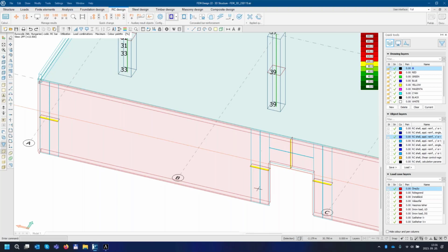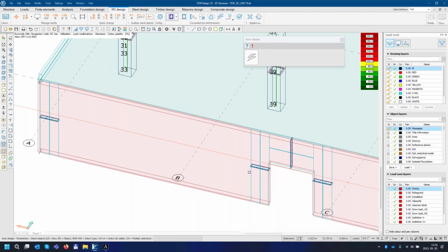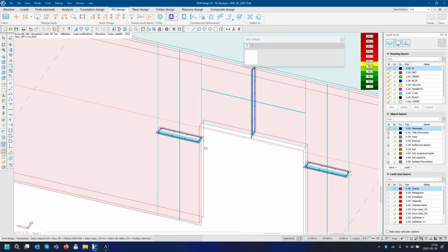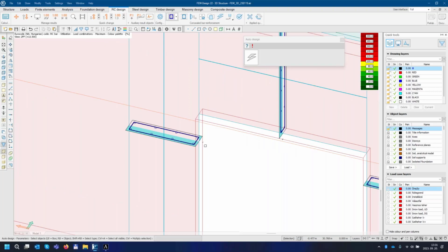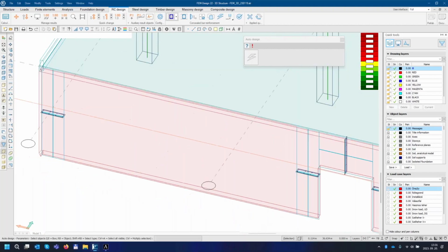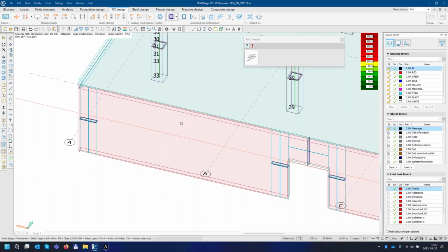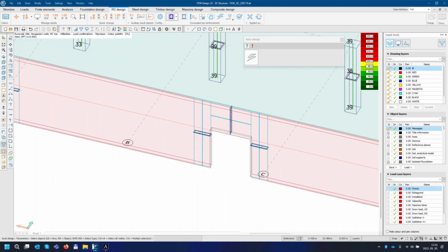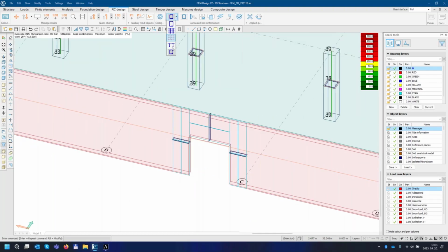So the big internal forces will be handled with these bar-type elements. You can set all the parameters like bar elements, and as a result, you will get reinforcement like columns and beams here. It's good because after that you don't have to make additional U-shaped bars to the edges, and you will only have to make some base mesh in the middle of the wall here.